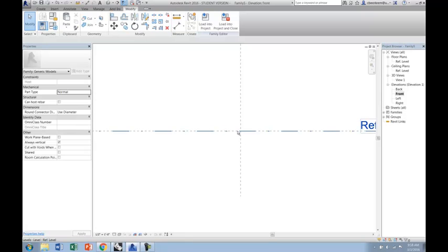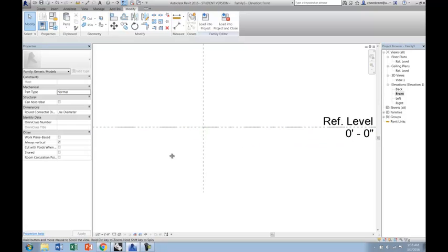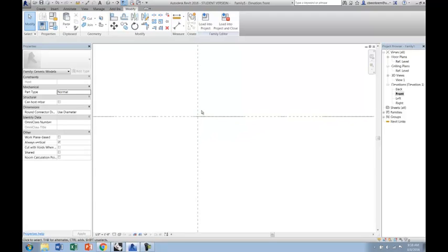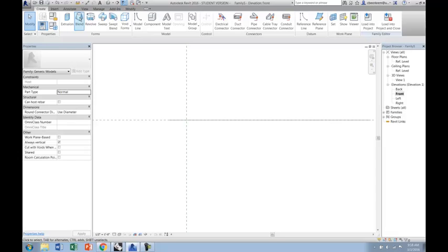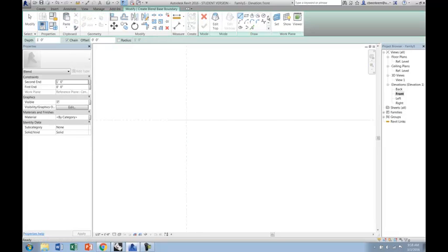And you can actually see when I am mousing over here that plane as well as the original reference plane. So we're just going to zoom in here towards the center and create a new blend. A solid blend is just like an extrusion with 2 profiles, kind of like a loft. You can see here right now we're editing the bottom, and then we'll hit the edit top button.